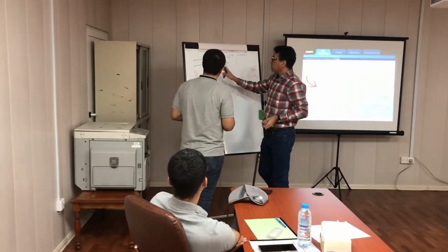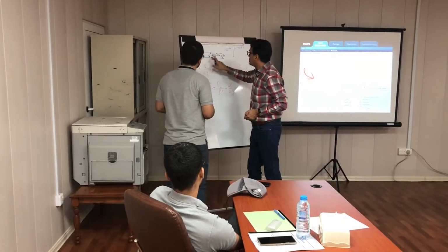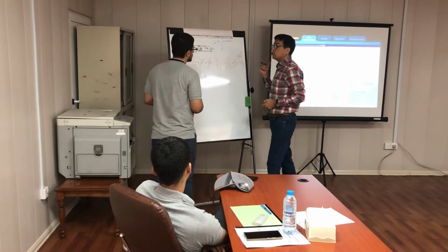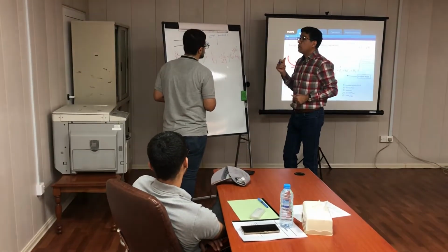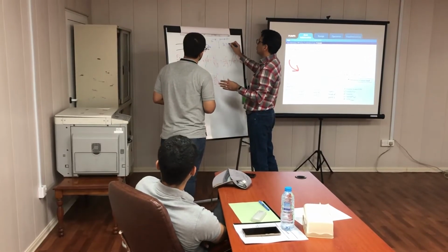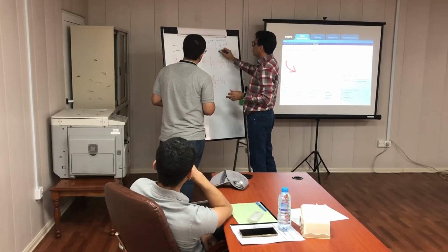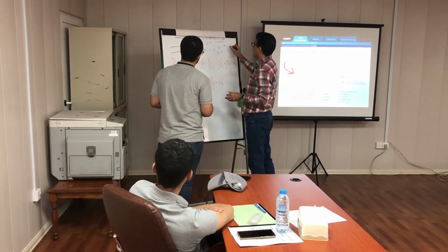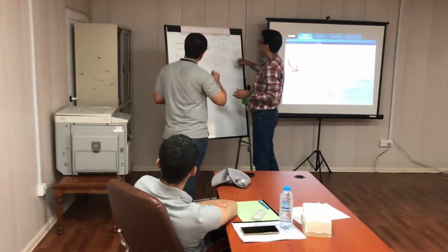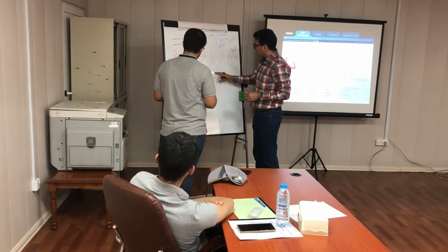You have an exit line here? No. The flow rate in these two sections is equal, and the diameter refers to the mass conservation law. That means Q1 is equal to Q2. Rho A V in situation 1 equals rho A V in situation 2. The rho is constant, the A is constant, that means the velocity is constant. Why did you write down the velocity?